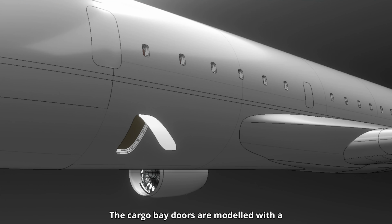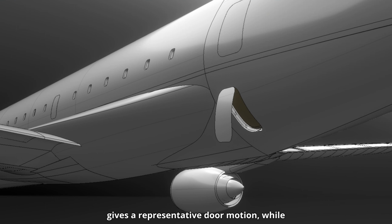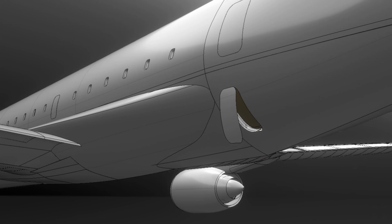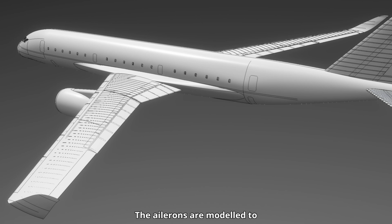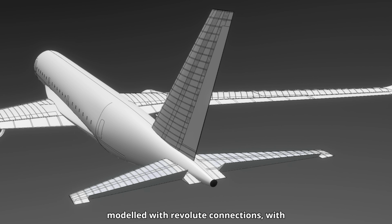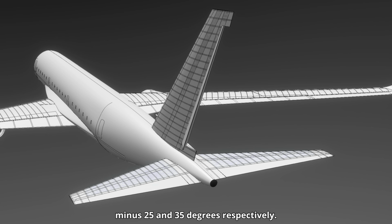The cargo bay doors are modeled with a revolute connection, allowing them to open outward to approximately 100 degrees before retracting closed again. This gives a representative door motion while keeping the rotation within a realistic operating range. The ailerons are modeled to counter-rotate using revolute connections, with deflections limited to approximately plus or minus 25 degrees. Similarly, the elevator and rudder are modeled with revolute connections, with deflections of approximately plus or minus 25 and 35 degrees respectively.